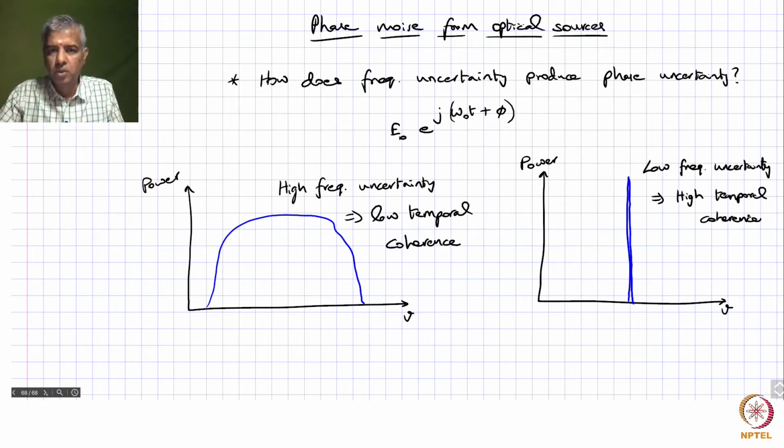Okay. So, that's one way of making sure that my phase uncertainty is relatively low, and through that I can possibly reduce the minimum detectable limit, or in other words pick up phase changes that are really small. Let's say in the order of 10 power -7, 10 power -8 radians. Okay, that would be quite desirable, but there is a fundamental limitation in terms of what is the lowest line width that you can achieve, what is the lowest phase uncertainty that you can achieve. And to understand that, you have to go back to lasers, laser theory, right. So, you basically say, what is a laser?